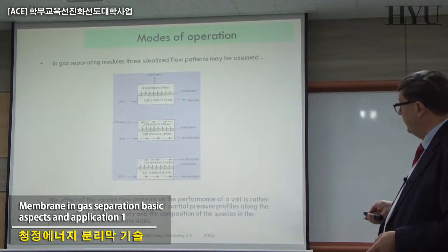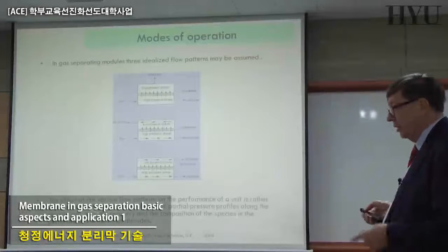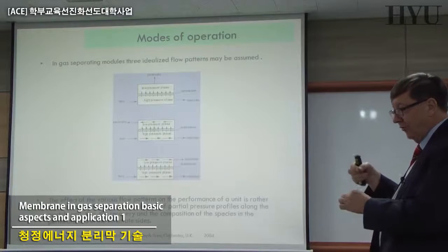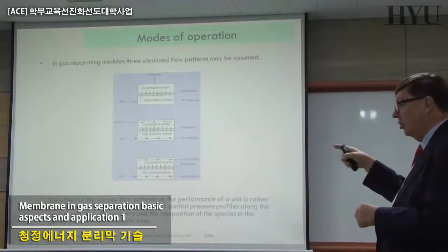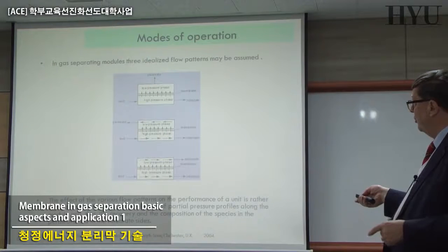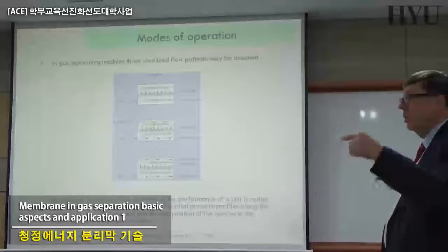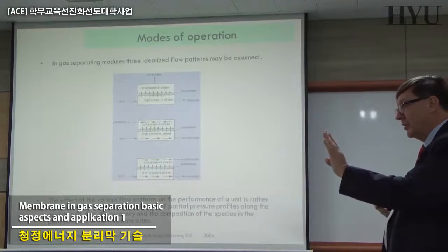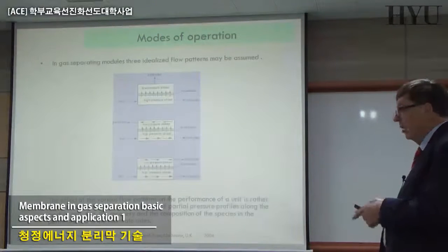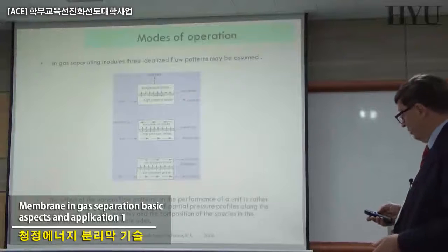Normally, in most cases, we are working counter current, because working counter current is much easier to keep the same driving force across the membranes along all the system. When you are working co-current, changing the concentration, etc., and changing the pressure drop along the module, you are also changing the driving force. So the system is a little bit more complicated to predict and to analyze. But depending on the case, both configurations can be of interest.